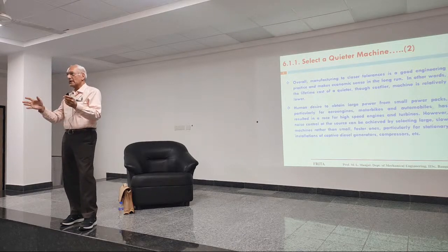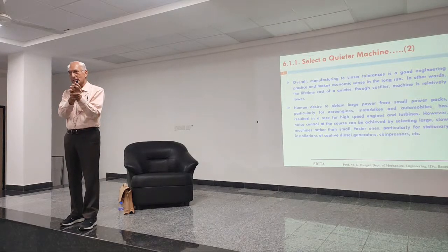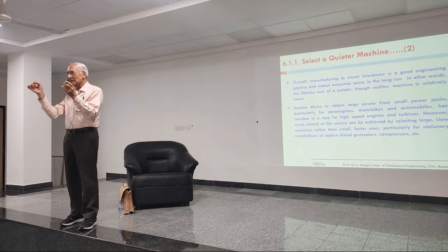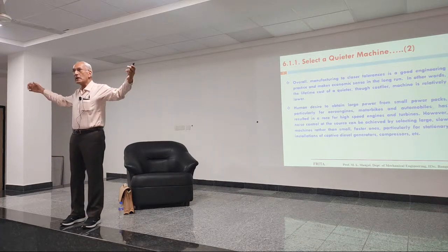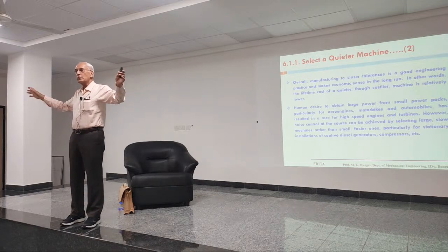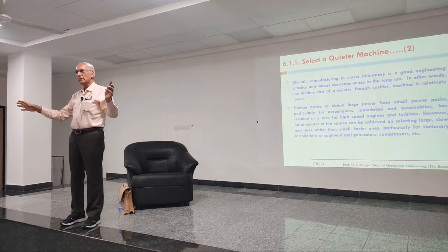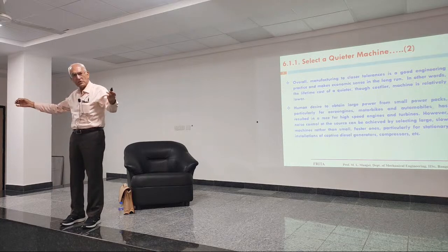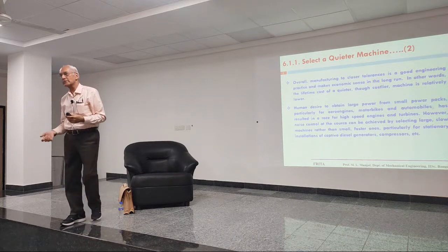Okay? Now, the unbalanced inertial forces are 1/100 of those of a normal engine. Second good thing is that those forces act on such a big engine, the mass is so much that there is no question of vibration isolators, nothing at all was needed. Because those forces are not even sufficient to shake this engine, leave aside any unbalanced force going to the ground.